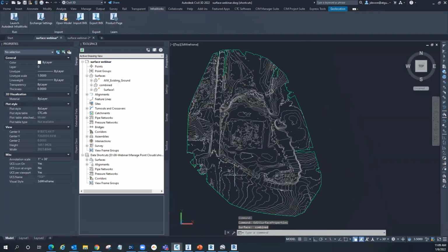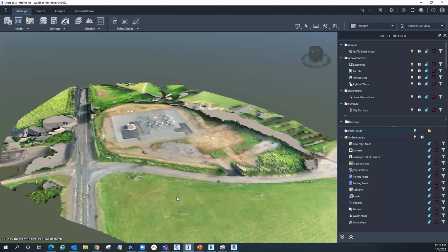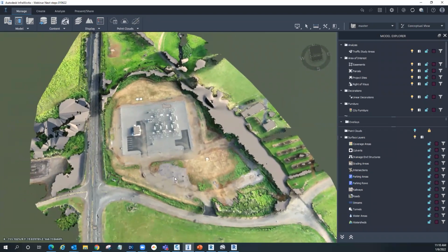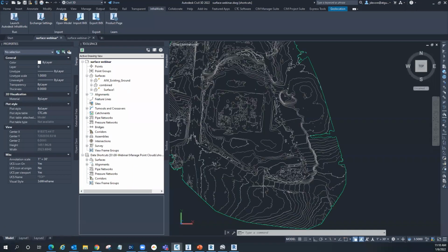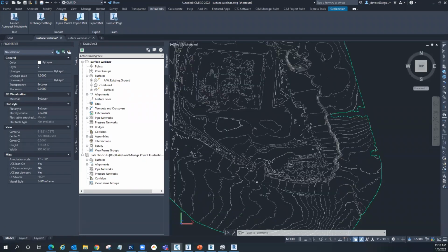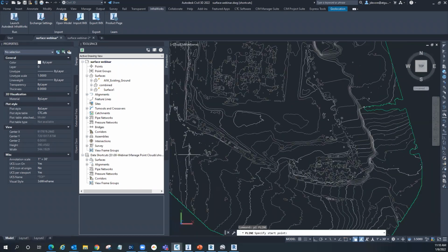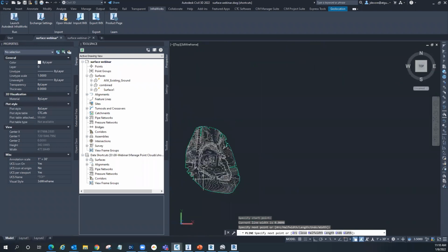Let's lay out some existing groundwork. We have two roadways here. If we look back at our reference, we've got a little highway, then a little dirt road, and then another one off into here. Let's go through what that workflow would be like in Civil 3D. First things first, we're going to need an alignment. There are a lot of different ways we can create that. I'm just going to trace a polyline and then offset that around here. I'm going to do this fast.